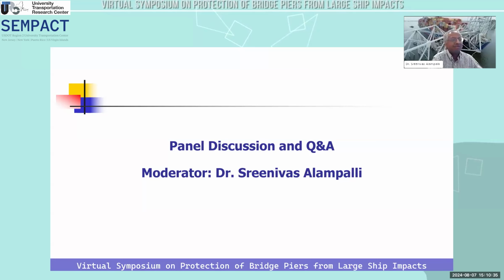Yeah, Mike Knott here. In my opinion, the best way to protect a bridge is to put something in front of the pier that deflects the vessel away from it. A protection system that can deflect the vessel is much more effective than a protection system that has to absorb the impact fully. A large amount of the collision energy is absorbed if we can get the hydrodynamic mass of the vessel being forced to turn or move. That's a great energy absorber rather than the structure itself.